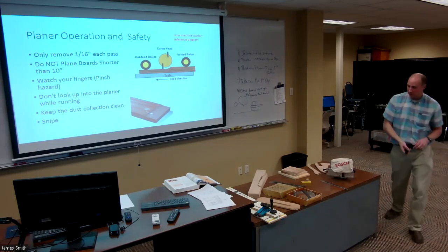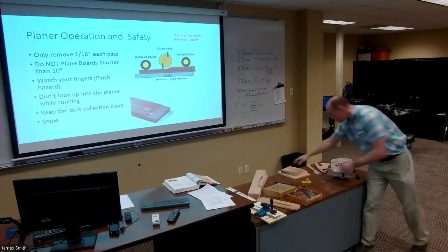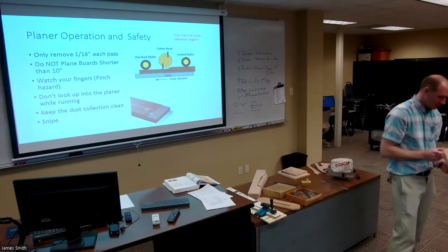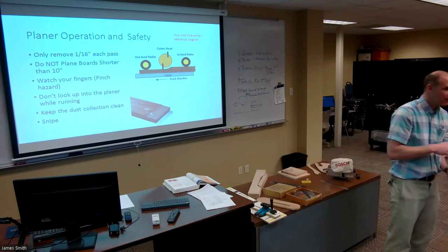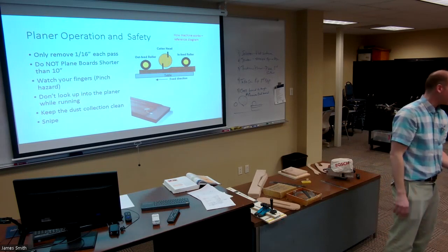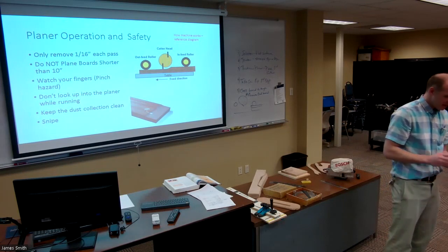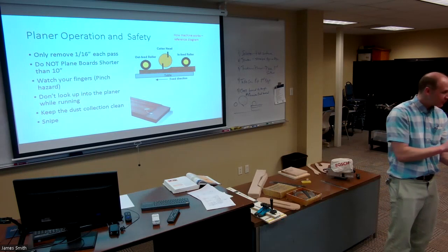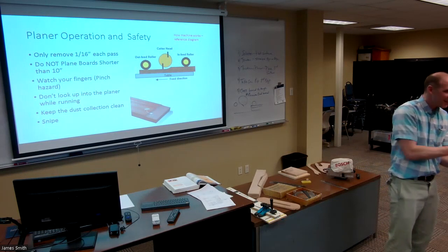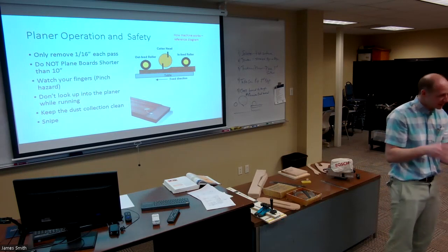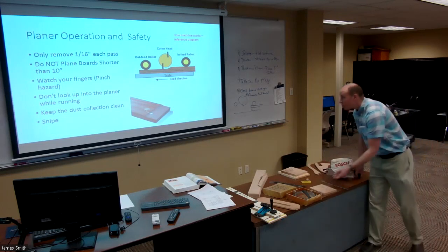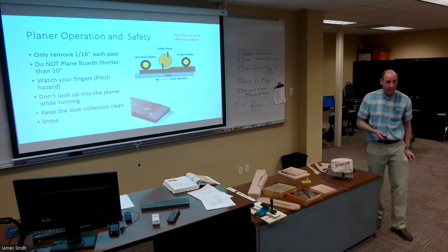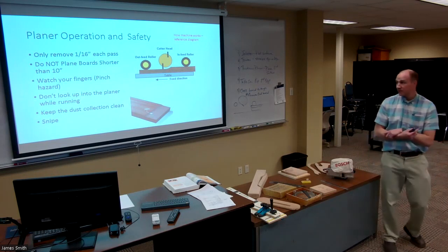Now, one thing I have found is, say for example, you have a board that's 8 inches. What happens if you turn it at an angle and run it this way? Sometimes you can make that work if you're in a pinch. But sometimes when it feeds through, those feed rollers have a tendency to, it doesn't necessarily feed in straight. So there's always a risk with that, okay? But as a general rule, I never send a board that's less than 10 inches through the planer.